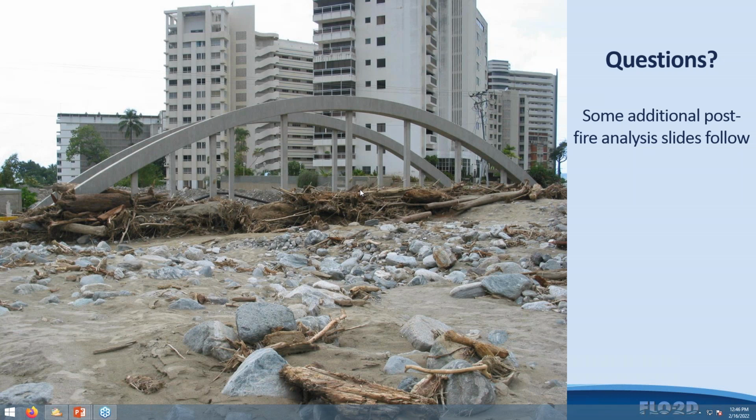And then over the alluvial fan, the frontal wave can be more than twice as large as the discharge on the rest of the recessional limb of the hydrograph, because the frontal wave became the peak flow. It's a very short, intense event, a feature of the mudflow event itself.